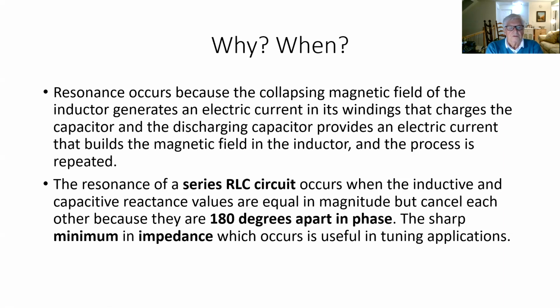Well, in a series RLC circuit, meaning a resistor, inductor, capacitor circuit, when the inductive and the capacitive reactance values are equal in magnitude but opposite in phase, they cancel each other out because they're 180 degrees apart in phase. There's a sharp minimum in impedance.